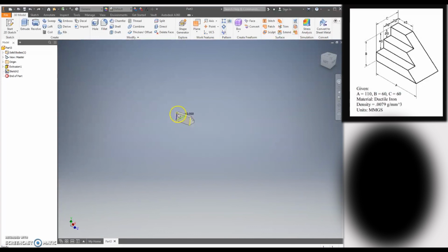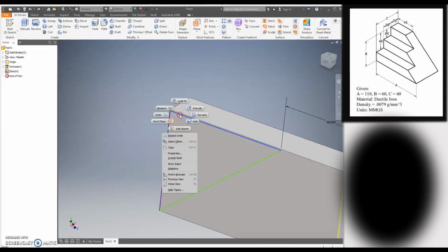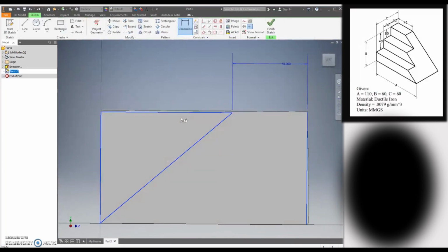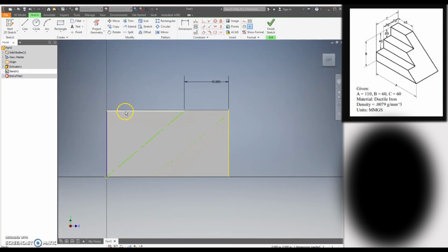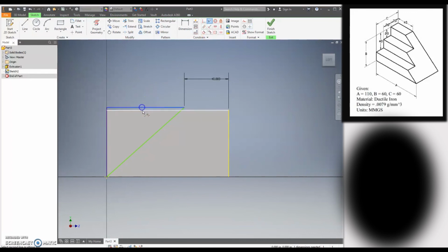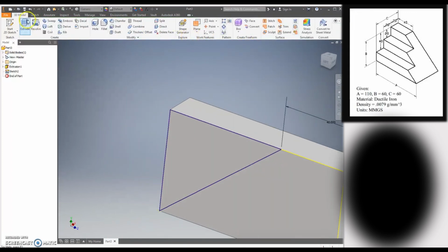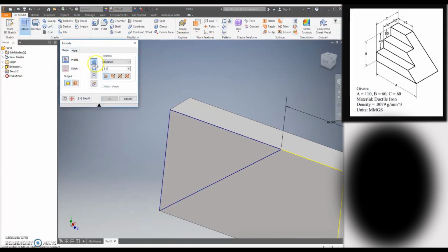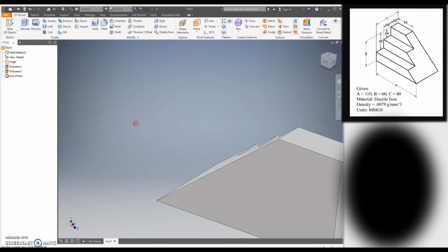All right, something's wrong here. Let's get in here and fix this. See this line? It's not on the edge. See what happens when you don't slow down? It's not attached there. I drew it too fast. So let's use some constraints. Collinear constraint. Boom. Just like that. What we just did, we told that line to be collinear to that edge. And it'll forever stay on that edge.